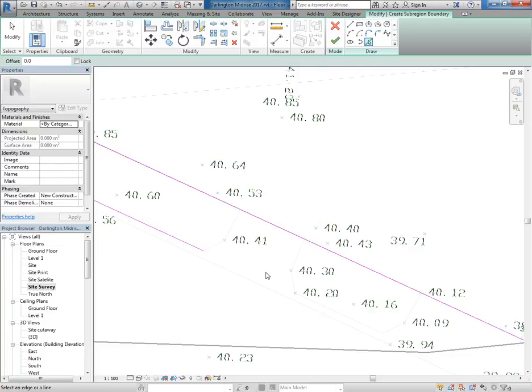Now, if you haven't done it the way that I've just been showing you, if you've tried to do it all in Revit, and you've done subregions, and then you have another subregion that is touching the subregion that you've done previously, it won't snap to it when you go to draw the new points for a start. It's just one of those things that Revit doesn't do. Revit won't let you have overlapping subregions. It's one of those annoying things.